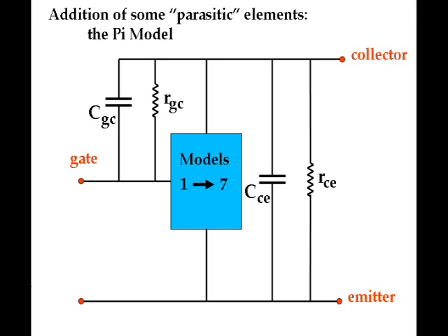I've been taken to task by some because this entire course employs BJTs represented by Model 4. Why aren't there any examples employing FETs? The answer is, there don't need to be any. Model 3 or Model 4 represents a BJT or an FET. The FET is a simpler special case with beta gone to infinity and alpha gone to 1. It's easy to throw a parameter out of the answer, but you can't put it back in without going through the solution again.